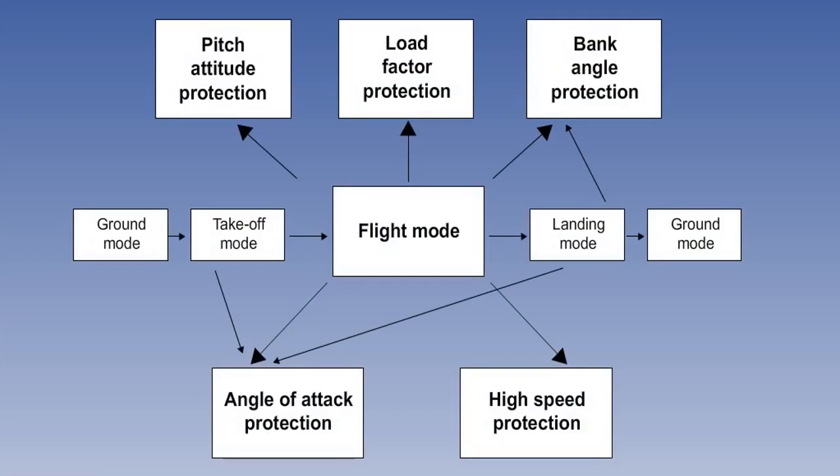In this lesson, you will learn how control laws protect a modern fly-by-wire aeroplane's flight envelope, and how similar protections are provided in a traditional aeroplane with the autopilot engaged. You will also learn the definition of a control law and the different flight envelope protections available.